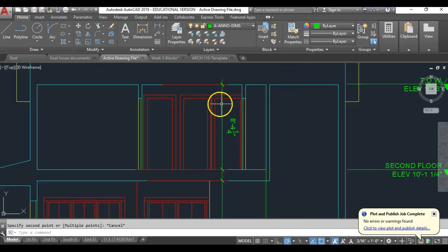Now, up in here, these are the three doors that are on the second floor. This is the door, so I'm cutting through the door here. That's the wall, and just like we do with windows, we show it in lighter line weight to show the door and the door thickness, and then these are the doors in elevations.